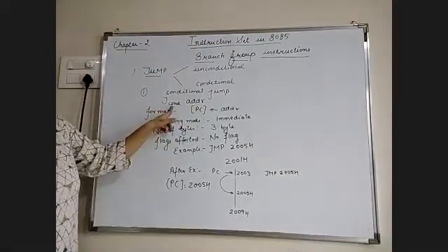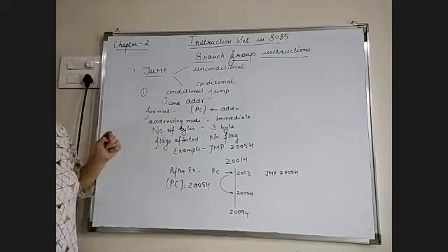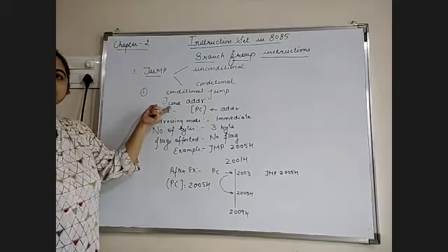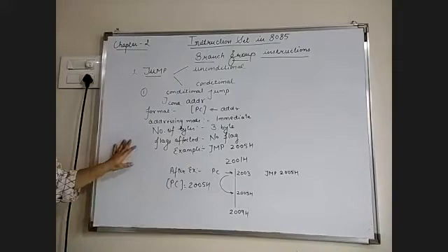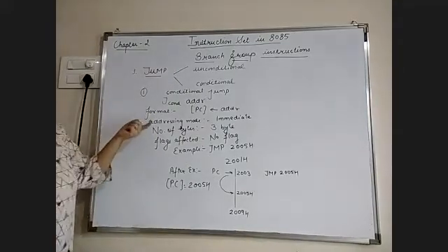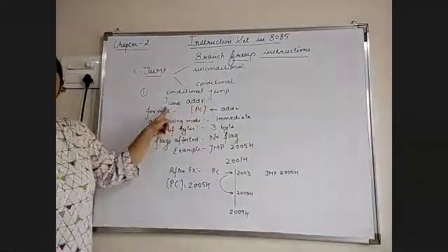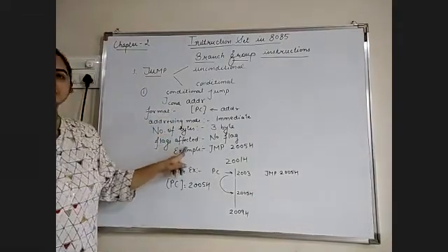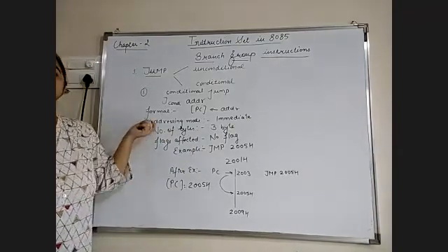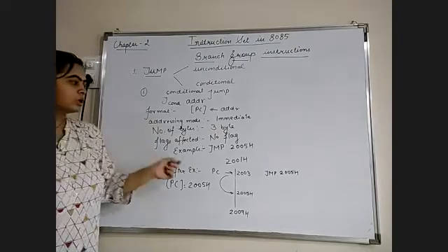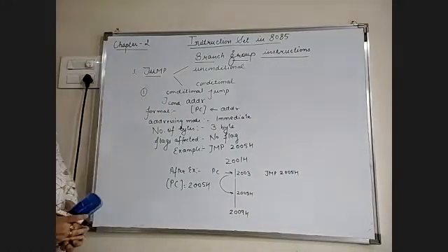Here we have a condition. We are not writing JMP, we are writing J condition, which I will tell you in tabular form. If the condition is satisfied, it will jump to the address given in the instruction. If the condition is not satisfied, it will stay in the main program only. The instruction will again occupy 3 bytes of memory, 2 bytes for the address and 1 byte for the opcode. Flags affected: again this is a branch group instruction, so the microprocessor only jumps from one location to another, and no flag will be affected by its execution. Next we can see the table first.